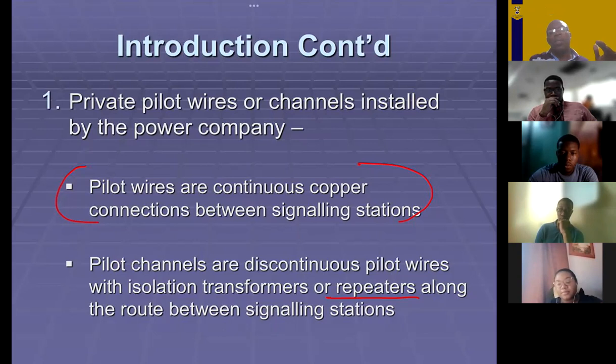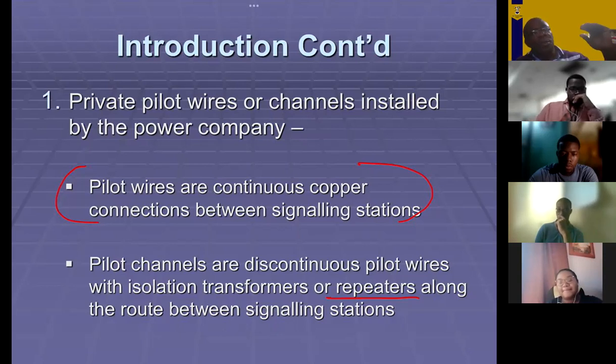If you then see something coming to you which was, say, below, I don't remember what the threshold was at the bottom end, but let us say it was now at 1 volt, that will be reproduced as 0. So you get back your ones and zeros, which you can then move on. Are we clear? So the repeater stations are looking for threshold values. You have a high threshold, you have a low threshold.